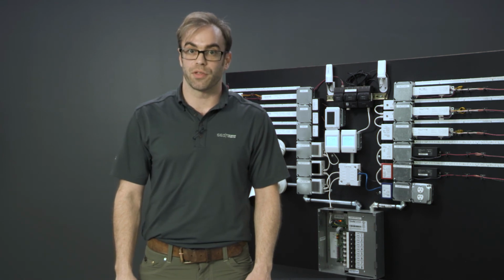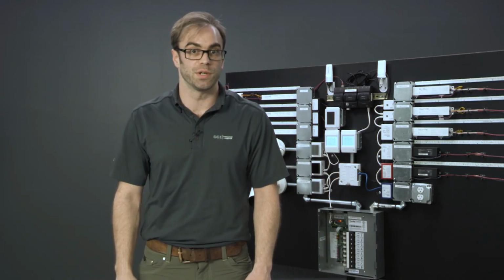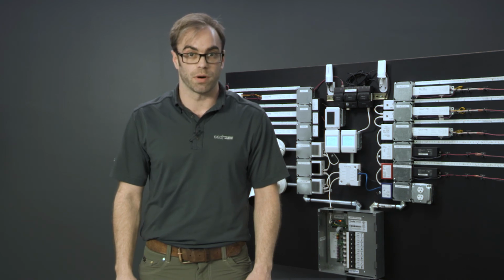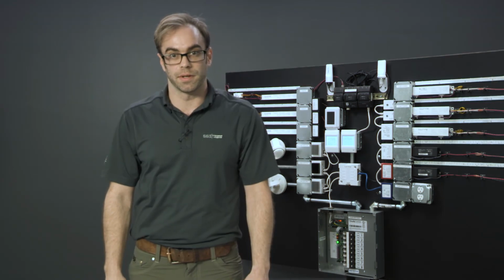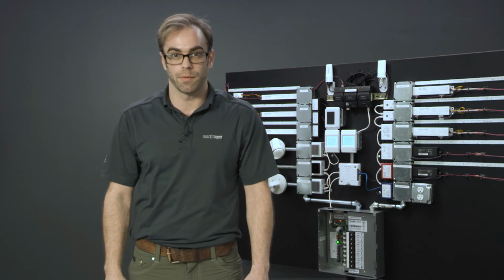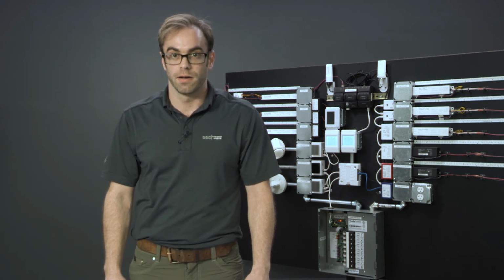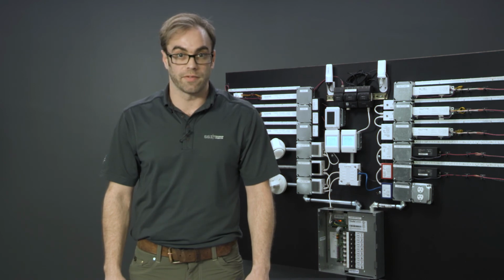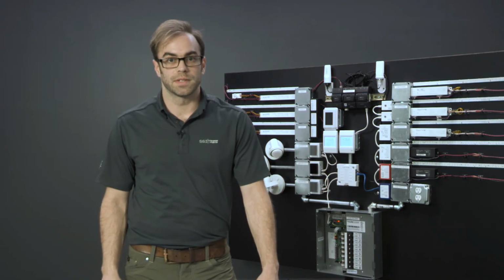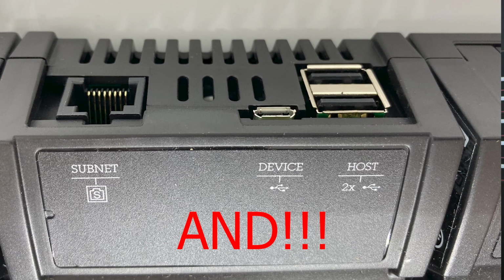The Eclipse does have a 3rd nLight port. However, this port is dedicated for use with the GFX G2 unit. You cannot connect any other nLight devices or nLight bridges off of this port. The Eclipse also has network capability. It has 2 Ethernet ports for which you can add the controller onto a local area network. As we've discussed, nLight carries voltage on its Cat5 wire, so you do not want to plug an nLight Cat5 cable into either of these 2 Ethernet ports. Lastly, the nLight Eclipse has 2 USB ports on top of the unit. This is where you would plug in the Wi-Fi antenna or nLight air adapter.